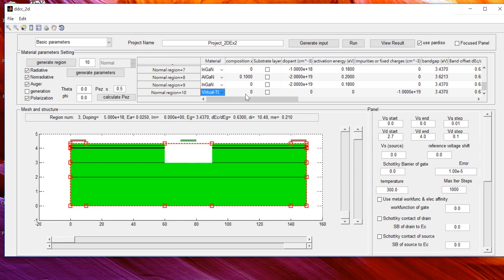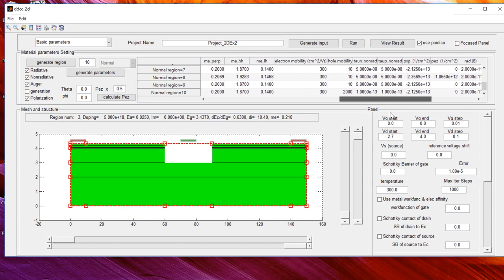So if you choose ITO P other, then the polarization will be 0. If you choose ITO P gan, it will set the same polarization as P gan, so they avoid it. Anyway, this is an artificial layer, so there's no special physics. Just want to represent the equivalent resistivity of the ITO. The non-radiative tau is 5e-8. Yeah, except don't change this one.